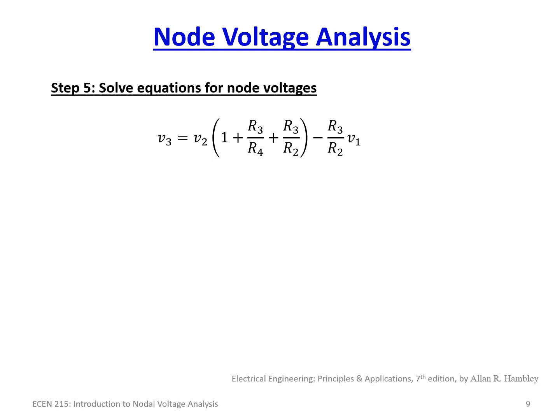So step 5 is simply solving the set of linear equations. Here we solve V3 in terms of V1 and V2, again V1 being a known value. And we just combine all the terms. We have taken this equation and simplified it a little bit, and we simplify it a little bit more, and we get V3 in terms of, again, R2. What I did here is I took 1 plus R3 over R4 plus R3 over R2 and just called it RY, just to simplify the math.